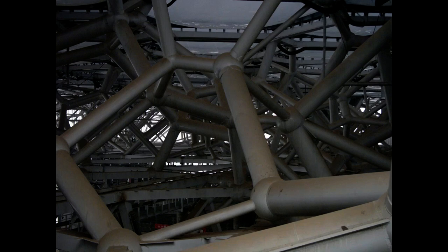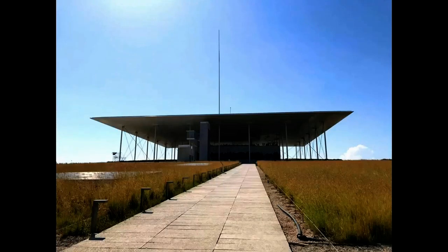It so happens that the Chinese had an awful lot of welders. So all of these nodes are welded connections, and of course the sphere often solves the problem. When you've got a lot of things meeting, coming in at funny angles, you do need that sphere at that point of intersection. It solves all the problems for you.